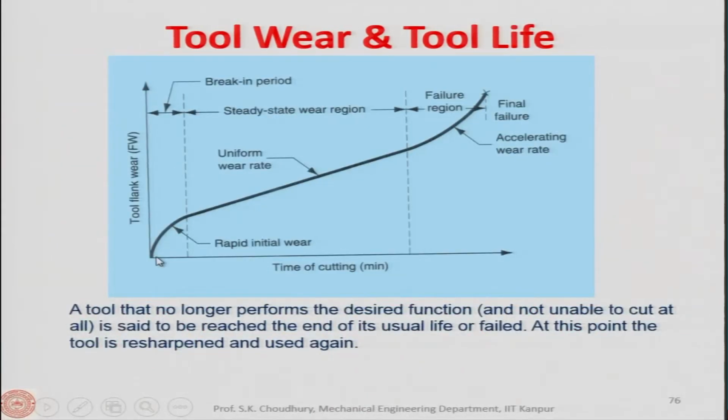I was talking about exactly this, that this is the tool flank wear, and as the time of cutting progresses, the tool flank wear progresses in this way. Here this curve will have 3 distinct zones. One zone is this, which is called the break in period or initial break in. Here it is a rapid initial wear.